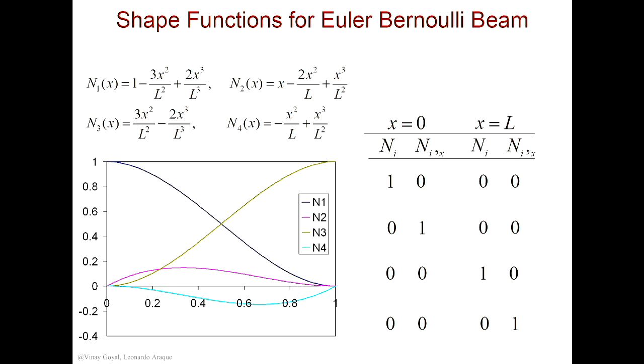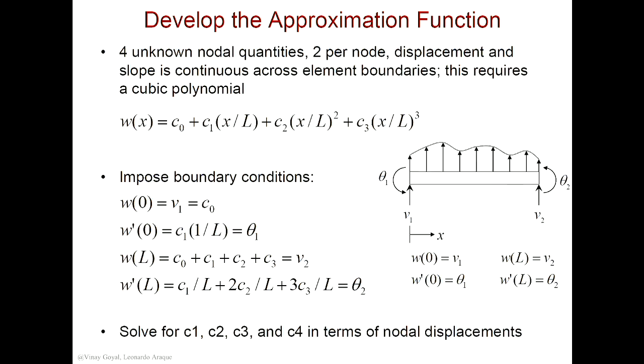In fact, it is complete, and I know that because we started with a full polynomial here. You see, I started with a full polynomial here. I didn't skip any terms. So it's complete. And I tried to enforce that by satisfying all the boundary conditions, and I came up with my 4 basis functions. So by doing that, it guarantees me that what I have is robust, complete, satisfies the Kronecker delta property, satisfies partition of unity.